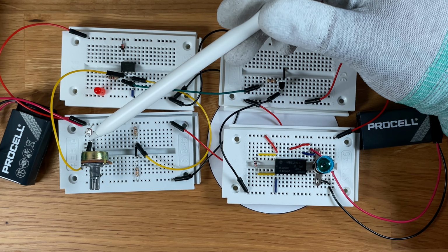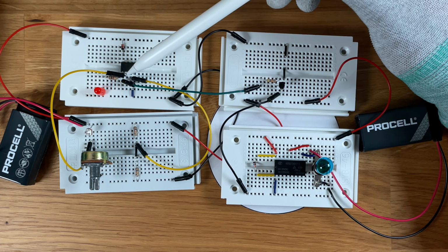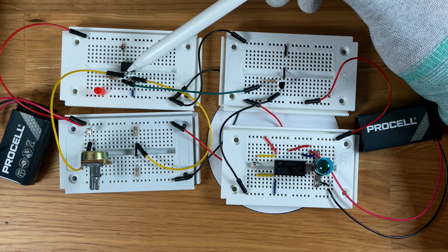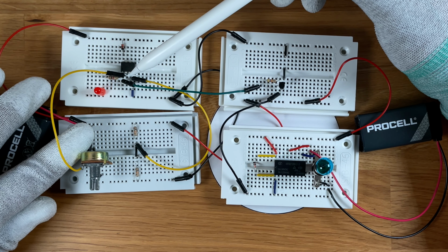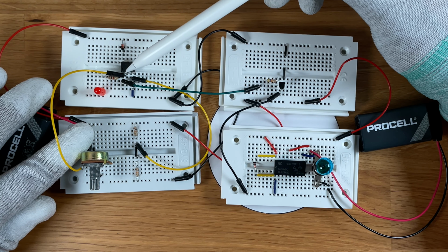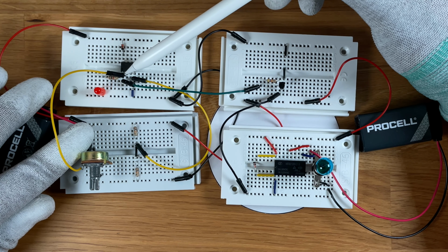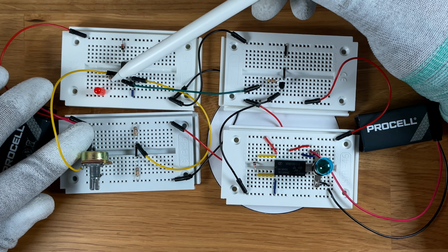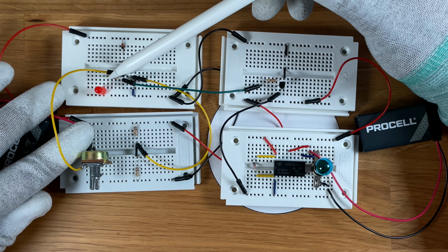So the idea is to use the yellow cables to go into the entrance of the operational amplifier, and as soon as we darken the light-dependent resistor like so, the voltage difference between the 2 entrances here becomes positive, which triggers the output, and the output leads to the resistor, which you can see here, and back to the negative terminal of the battery.